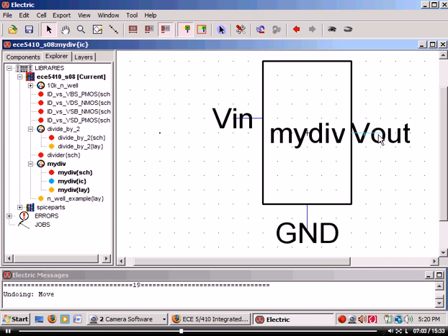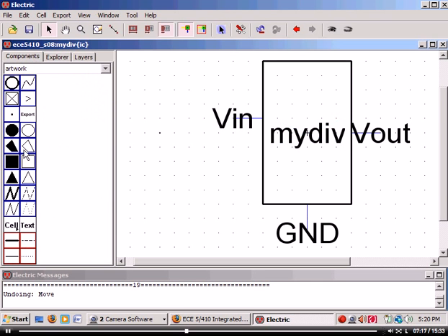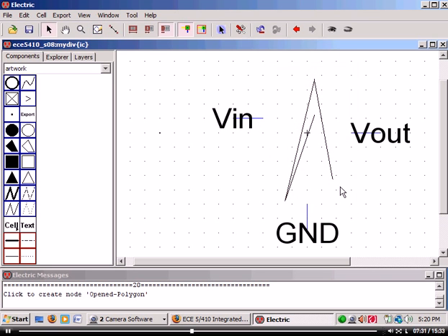Okay? This pin, this label here, goes away when I connect to it. So if I want to label, or I want to see that it's got a label, I've got to put annotation text in here. I might as well put some annotation text in while I'm at it. Oh, it's showing artwork. Well, now I know I can go in and I can drop something in. I can press Y. I can move it around. I can make whatever shape I want. You know what? I can even get rid of, press Y again, I can even get rid of that box. Then I can go edit this, press Y, draw my little, let's do that, right click, go up, whatever symbol I want, and leave it at that, press Y when I'm done.